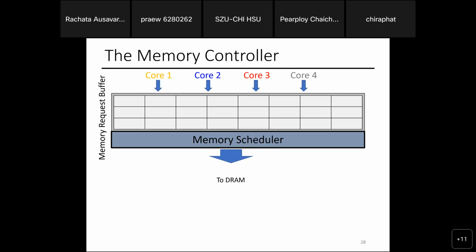So we actually have a lot of papers on DRAM refresh and how to reduce that overhead. Because imagine when you have DRAM that's like 64 gigabytes, for example, you spend 4x more time refreshing. So this is going to get worse and worse. There are works that look into how to make it cheaper so that when you buy a big DRAM, you don't feel that effect.